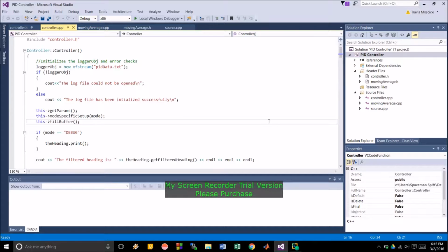That error term goes into your control system: PID controller, sliding mode, robust, feed forward. You've got all these options for controllers. Then the control signal, the forces that you want to generate, gets fed into your plant or your system model. After you send those forces through your model, it gets run back in, and that's how you have a closed loop, or feedback, system.